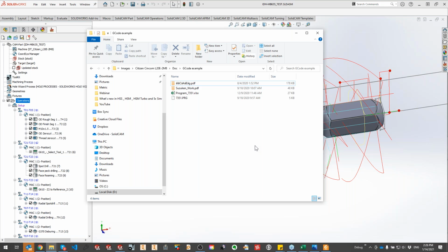So in many cases, it's very important that you have an experienced person for the Swiss. To handle one Swiss type post-processor case, it really depends on the operator himself. If you have a very high-end experienced operator, most likely the information that you get from this person will be viable for you to make a post. Of course, there are different sources for getting information in order to make a post. So as I said, the operator on the machine is very, very important.